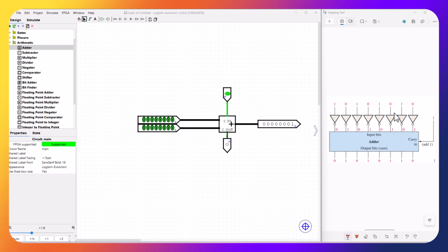You see it here, and so we're going to recreate this using Logisim. One way to do that is to use a bunch of these inverters. Okay, so I just make them point down. I'm going to make them small so they don't take up much space. Okay, make a copy.